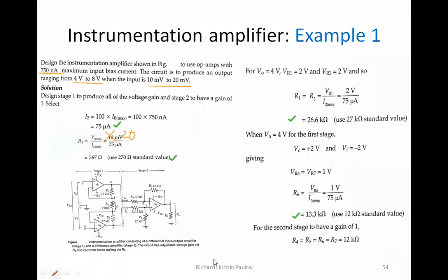Remember, we used to do some computer based circuit analysis, right? In that also we were getting standard forms of values, right? So we were able to compare the practical values and the theoretical values. So the computer helps us analyze and get nearly the same values. Okay, so we are going to stick with keeping all the resistances for having a gain of 1, ACL is equal to 1. So all of these resistances are going to be put as 12 kilo ohms.